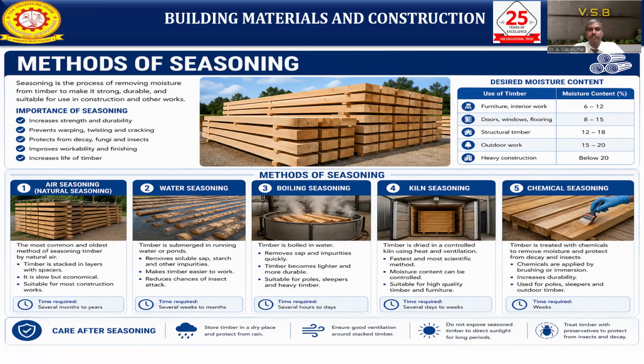We have five different types of seasoning. The first one is air seasoning, called natural air seasoning. It is the most common and oldest method of seasoning timber using natural conditions. After cutting to the required shape, the timber is kept in the open atmosphere, so the air itself removes the moisture. That is called natural seasoning.